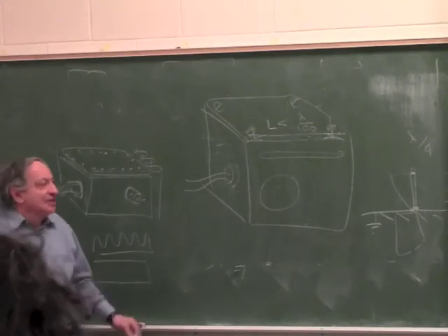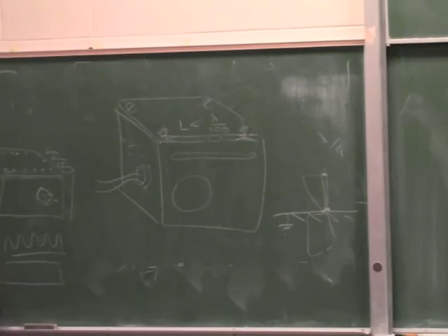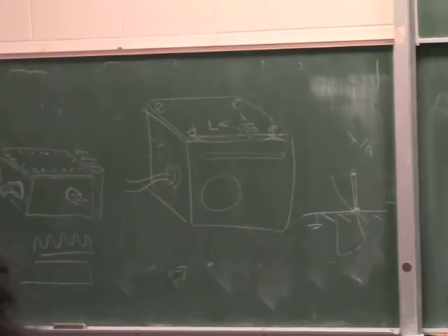Okay, so remember, this only starts showing up at tens of megahertz. So usually servo systems, sensors, you don't run into this problem because you typically work at kilohertz, not at megahertz. But sometimes you have a sensor which transmits wirelessly, and then you have to worry about this.